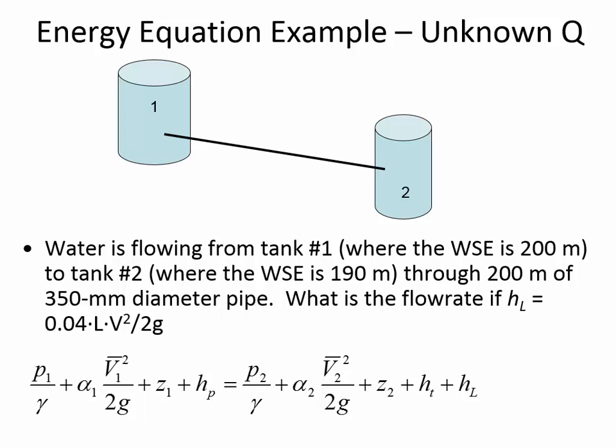All right, the pressure is 0 because this is air above it, and so it's going to simplify my calculations. I'm going to be able to cancel out the pressure head term, and I also know the elevations there, so the z term is known. And the other thing that's great is there's no velocity at location 1 or location 2. I mean, the water level's falling a little bit, but you've done problems having to do with how quickly tanks empty, like 1 centimeter per second. The velocities are so low. The velocity's going down here as this tank empties, and it's going up a little bit here as that tank fills. But these tanks are so huge that we can assume the velocities are 0.